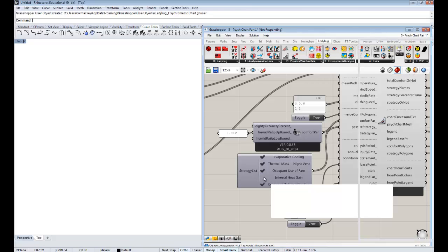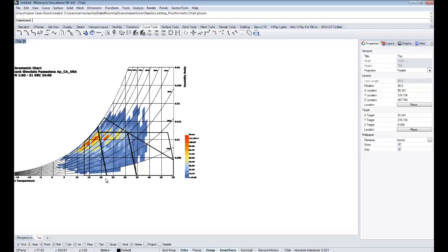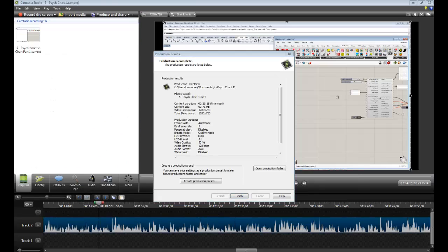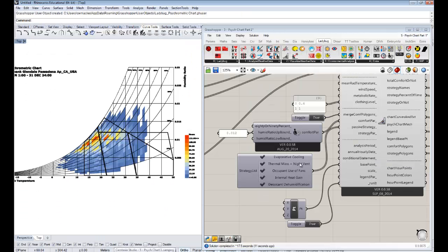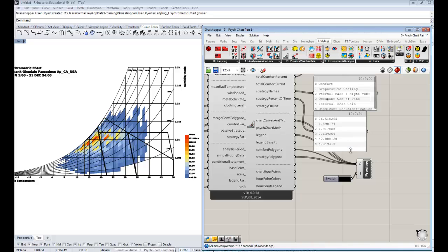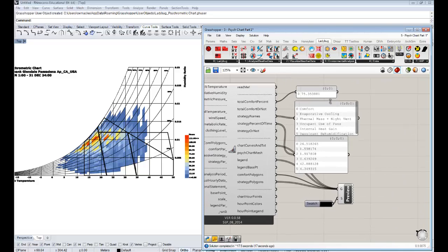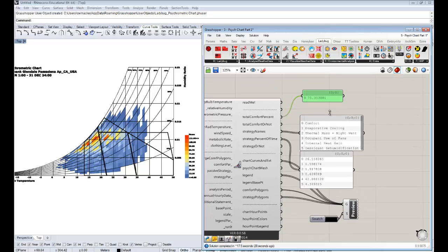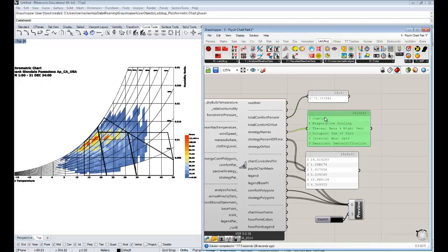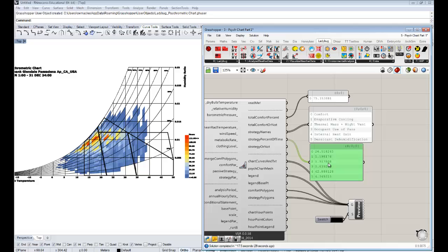And you see, if I check that, then we nab a whole bunch of extra times of the year, particularly, I'm guessing, more in the winter. And you can see what percentage that is? That is a whopping 42%. That is a lot. And you can see all together, we can get 75% of the hours of the Burbank climate comfortable with just these passive strategies without having to resort to air conditioning or heating and cooling. And maybe, if these are the only hours that we're really worried about, this isn't really enough to merit having to put in an air conditioning system.